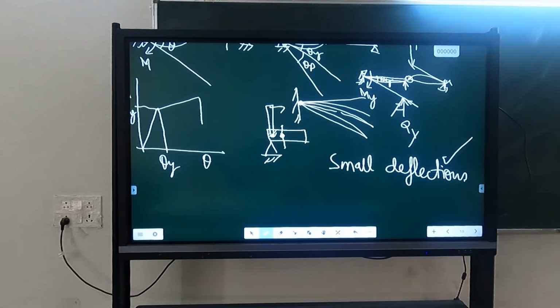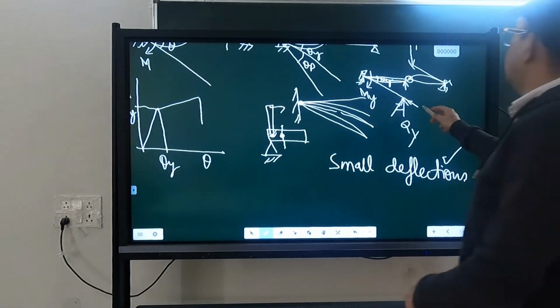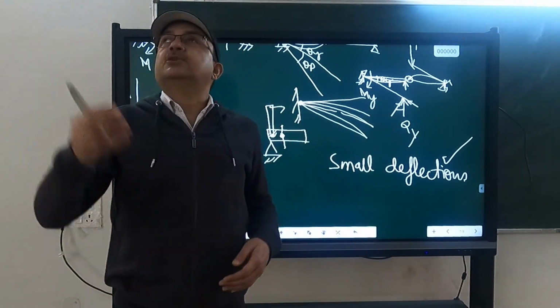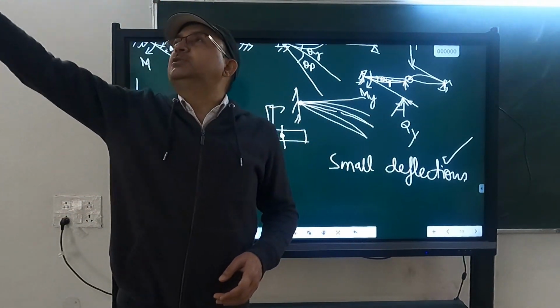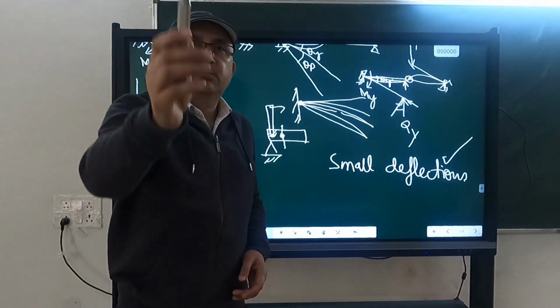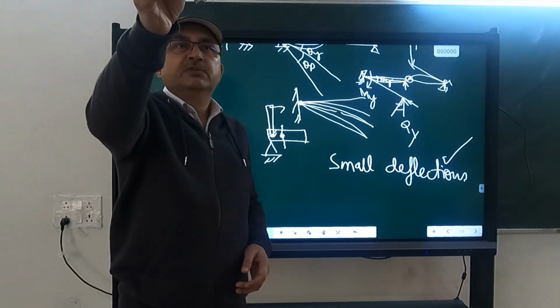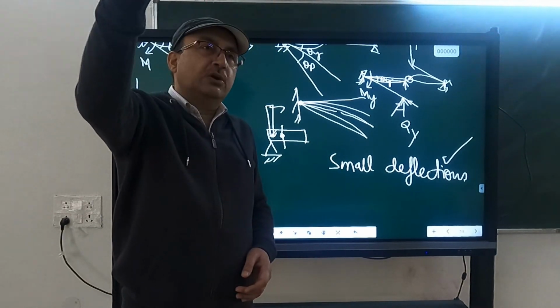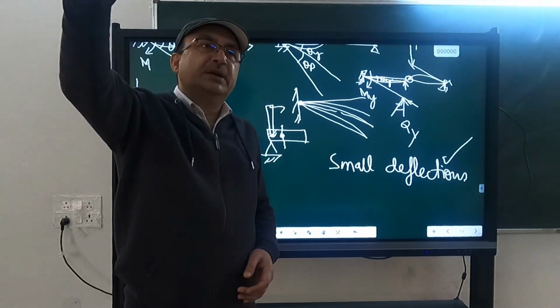It is similar. And then why you are taking that Q force at an inclined manner? No, I am not taking inclined. I have taken it vertical. I am just showing that this vertical load will have two components. If I am considering that the rotation of the beam is large, suppose this beam was coming here, then what will happen? The vertical load will have two components, one perpendicular and one along. So this along will cause axial load, perpendicular will cause bending moment.